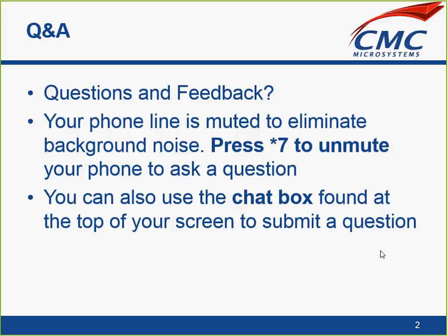Mark, there are some questions in the chat box. There's a question here: can we measure mixer noise with the PNA-X? If you're talking about noise figure, we can measure noise figure with a mixer. That's the NFX technique that I showed you earlier in one of the slides, where we do have a measurement class available to make noise figure measurements over a receiver, an up converter, or down converter. If you're talking about mixer noise as in noise power by itself, that technique is more of a receiver technique.